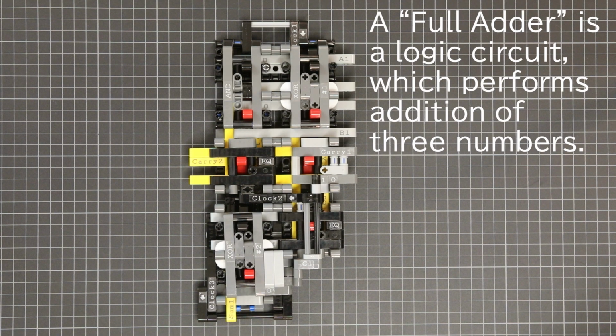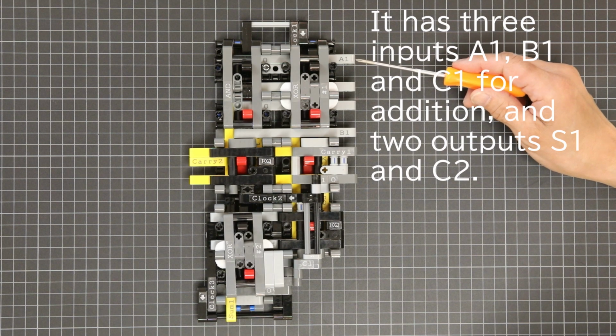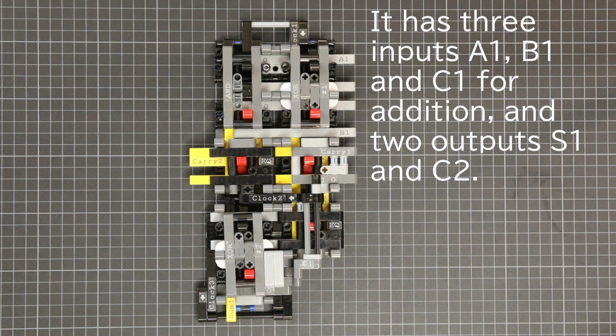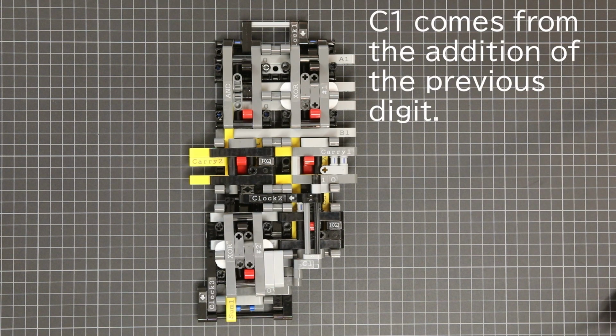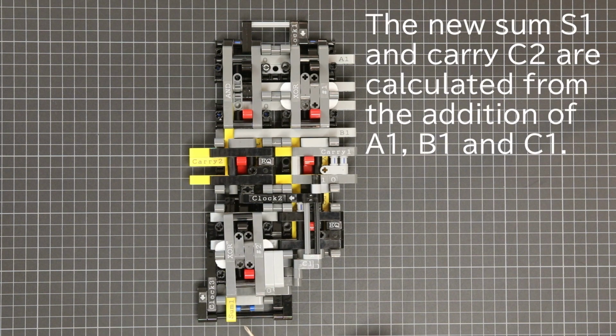A full adder is a logic circuit which performs addition of three numbers. It has three inputs, A1, B1, and C1 for addition, and two outputs, S1 and C2. Inputs A1 and B1 are single-bit binary numbers. C1 comes from the addition of the previous digit. The new sum S1 and carry C2 are calculated from the addition of A1, B1, and C1.